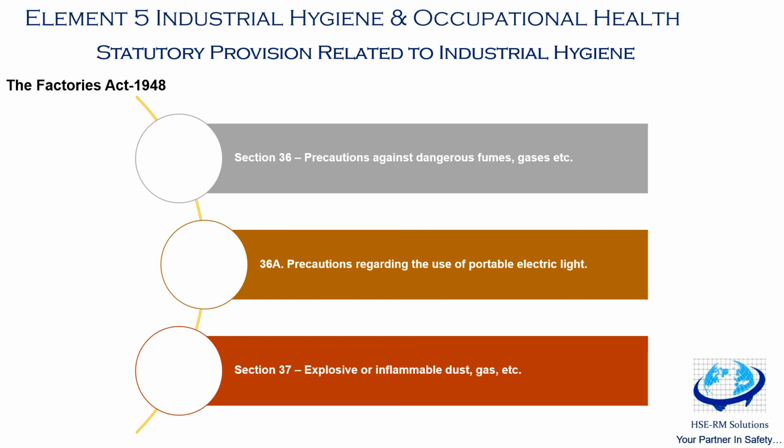Now, where in any factory the plant or machinery used in the process, as referred to in subsection 1, that is what we discussed, is not so constructed as to withstand the probable pressure which such an explosion would produce, all practicable measures shall be taken to restrict the spread and effect of the explosion by provision in the plant or machinery of chokes, baffles, vents and other effective appliances.